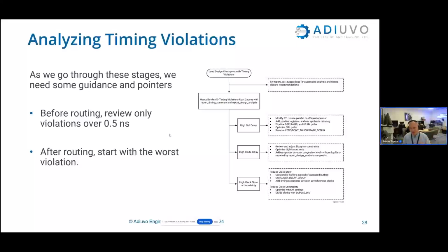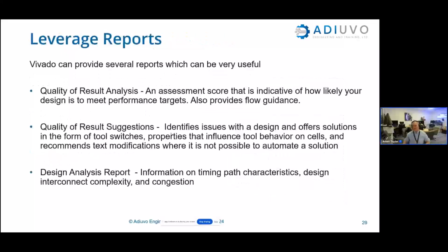That's the approach we're going to take. We can take a look at the high cell count, the route delays, and so on. As far as I'm aware, these steps are available in project mode and non-project mode. We're running through the same processes, whether you're doing it in the GUI, as I'm going to show for the example because it's more illustrative, or whether you go through a scripted project or non-project mode. All these steps are still there and viable.